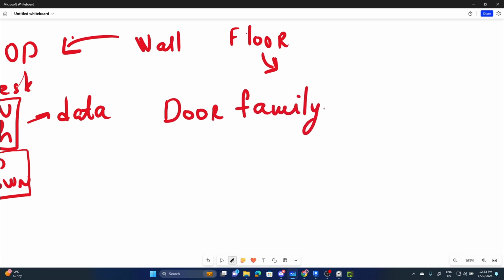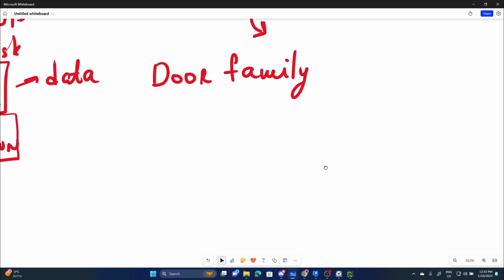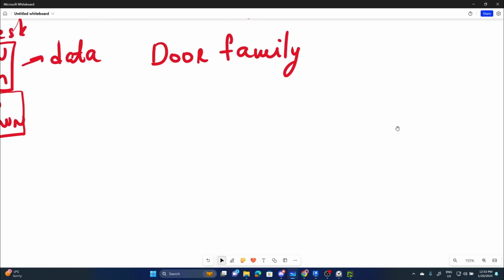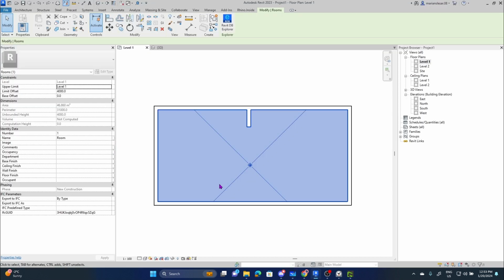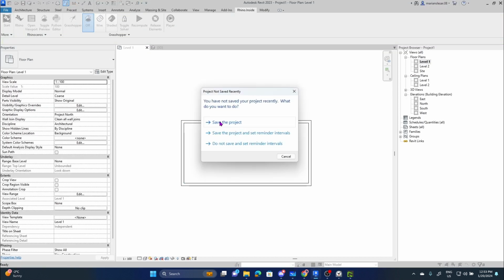So we've got to create a door family. You can go about this using different approaches, right? The first approach may be, you know what, just open the door family file, which will be like a container of objects, and then you just put a bunch of geometry. So you model just geometry, like an extrusion that represents the panel, an extrusion that represents the handle, and different kinds of sweeps, extrusions, whatever you want, right? I think if we do this, maybe do this pretty quickly.